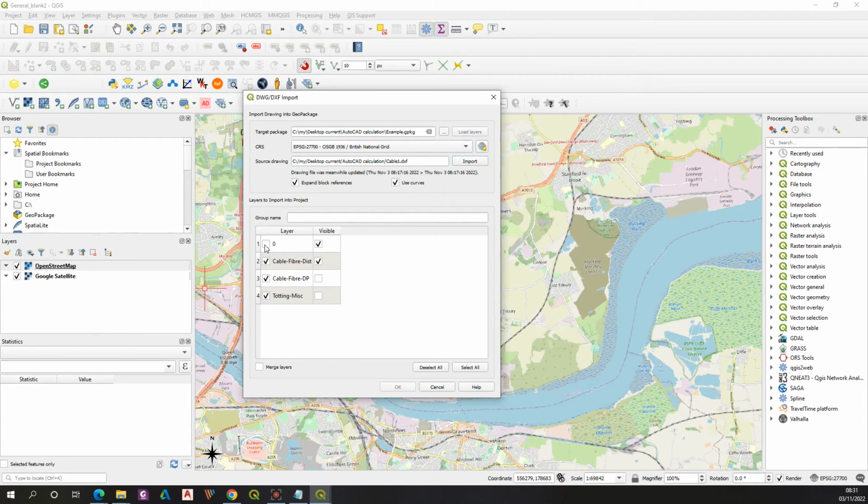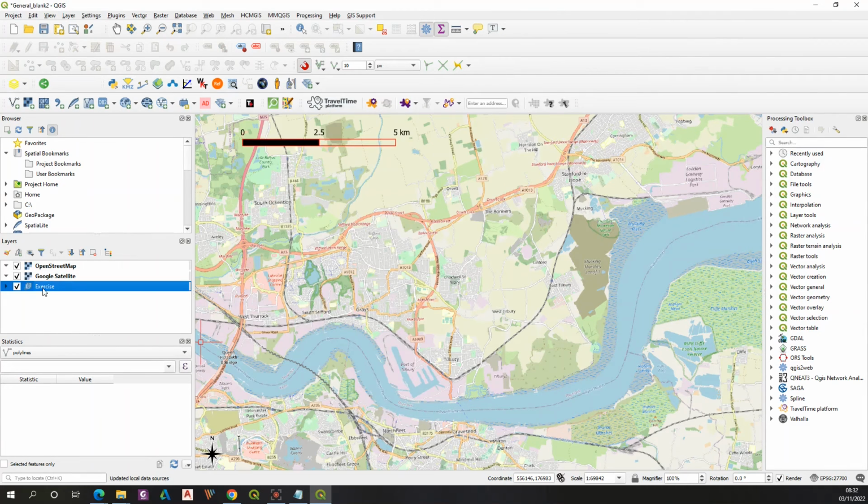So what we need to do right now, we just need to keep this one particular layer, which will be used for auto calculation of our distances. So therefore we need to switch all the other layers off. When everything is alright, make sure that your group name is provided and hit OK. Now you can see that your layer group has emerged in the panel, which is great. By dropping down, we have another group embedded, and obviously the polylines layer.